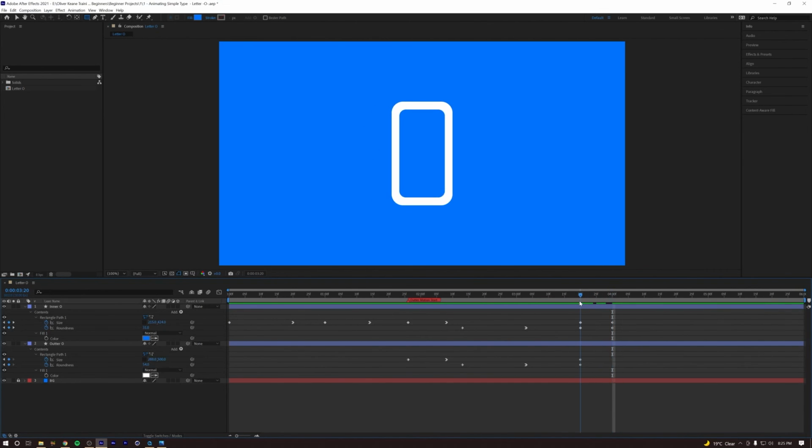and then we have to do the same thing with the outer. So we actually need to change back the size. So the size of this was 500 at the start, see right here, because we started animating this, where it says outer motion start. So it was 500 by 500, and now at the moment it's 288 by 500. So we need to go back and add in here 500 to the size, and then the roundness needs to be what it was, because now it's 54, it needs to be 250. So going back here and just go 250.